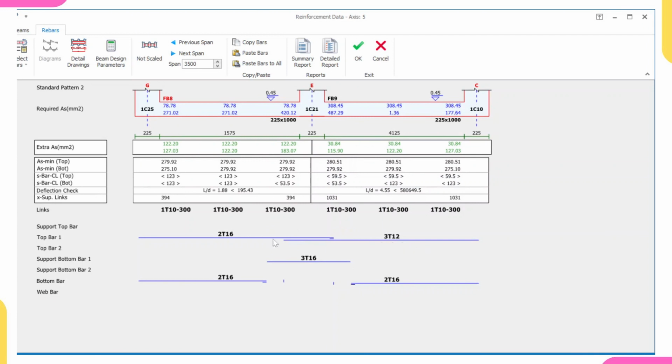So this is one of our beams. If you can see, in a normal beam, we will be having hogging moment at the top. Yes, we'll be having hogging moment at the top. But now that moment is no longer at the top, it is now at the bottom. Yes, this is also another unique thing about this beam raft foundation. But if it is a normal beam, all our superstructure beams, all these 3Y16 will be at the top, will be here, because more moments will be at the top.